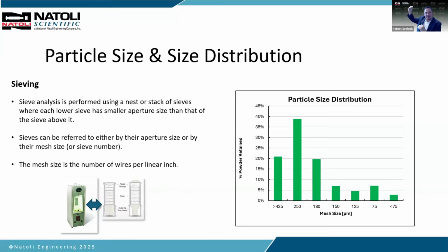If you've got an excessive amount of fine particles, they're going to have trouble bonding during compaction. They might have some flow issues. They might cause sticking, because if they're not bonding to each other, they'll adhere to your punch face. So excessive fines is our enemy.